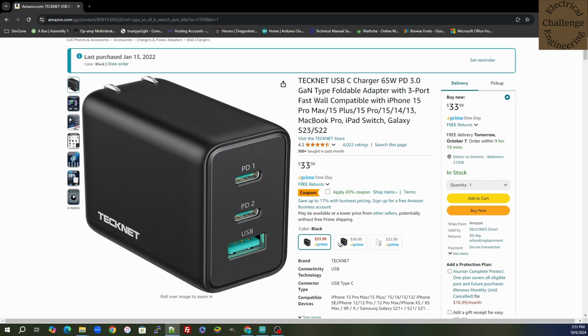So this is the USB-C brick that we'll be using as our DFP, as our source. I couldn't find any specs on this Amazon website, and I couldn't take a picture of it because the print's really small. But it has 5 options listed on the device, which are 5 volts at 3 amps, 9 volts at 3 amps, 12 volts at 3 amps, 15 volts at 3 amps, or 20 volts at 3.25 amps to give us the 65 watt output. So it comes with all of these fixed PDOs that we'd be able to choose from when we start the communication protocol.